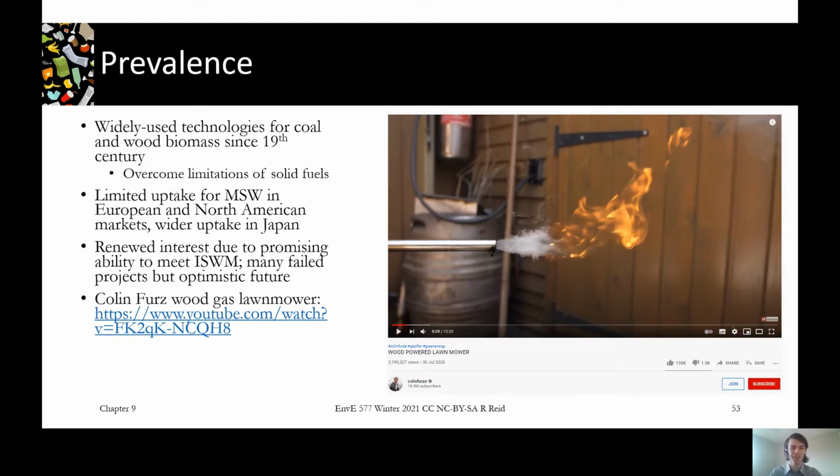And there's a really interesting video that I've shared here. There's a YouTuber, Colin Furze, who's like a maker and makes all these weird inventions. And he's modified a lawnmower to run on wood gas. And it's kind of interesting to see how he puts it together and some of the operational considerations that he needed to take into account to run on wood gas. And you can really see how the three products of pyrolysis come out in there. You'll see all this tar, which is the liquidy oil product, sticking up the machine, as well as the flammable gas, which you can see in the picture, and then the char left over and ash from the solids. So pretty interesting video, which will give you a really good sense of how you'd actually do this at a small scale.